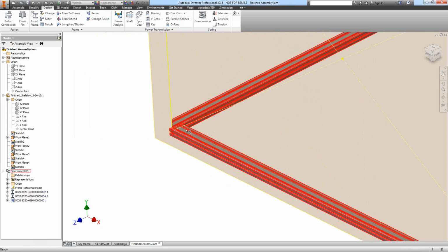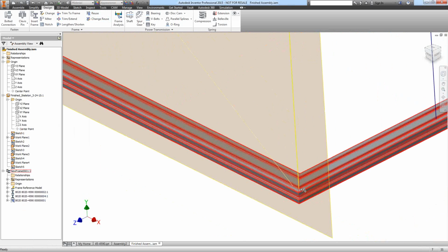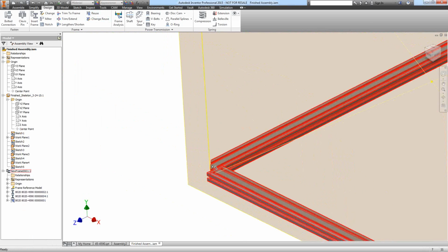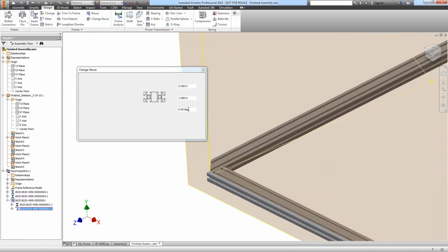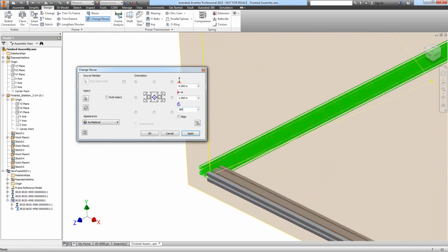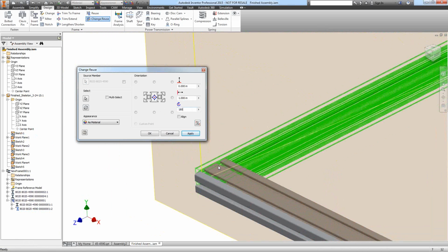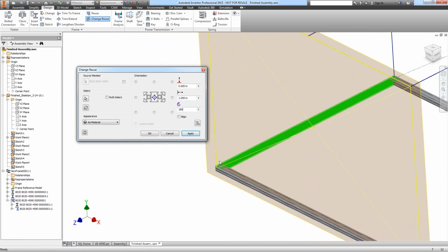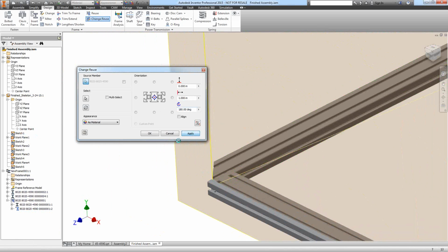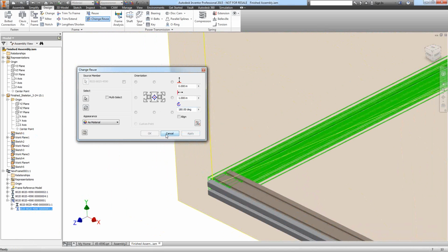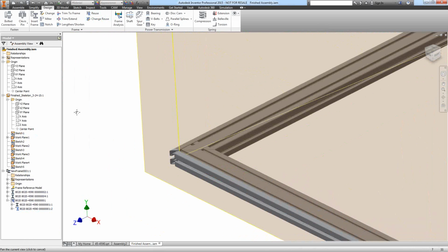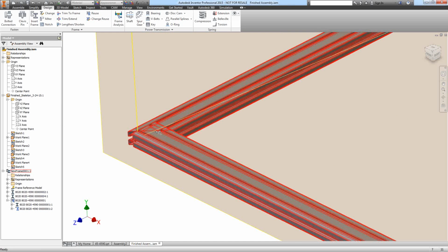But you notice what happened. The miter that was on the original, of course, carries over to this one because they're the same part file. But it's flipped the wrong direction. So what I may ultimately need to do is either mirror or rotate. Let's just try 180 here. Unfortunately, you notice the preview that I get, I don't see the miter in the preview. So you may have to guess a little bit when you use reuse, but ultimately that now does the trick.